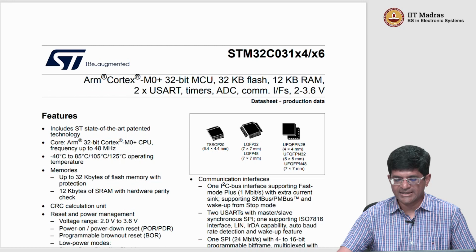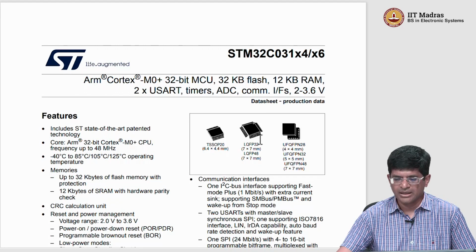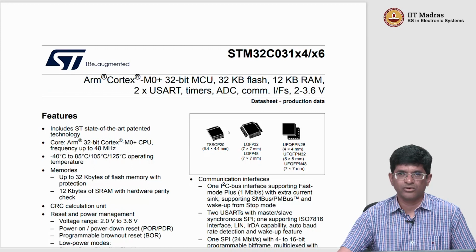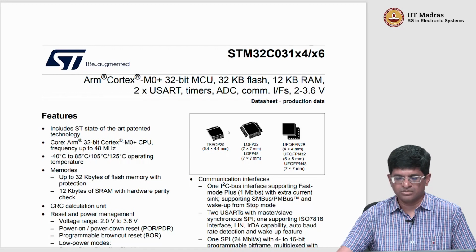One of them is called a TSSOP, another one is the LQFP, that's the low quad flat package. Then there is the UFQFP, which if you look carefully at it, you will see that the pins over here are actually literally almost under the package. These two are, and in fact all of these are meant for what is called surface mount technology for the PCB design, which is the most common form for any even slightly complex PCB, especially involving microcontrollers and so on.